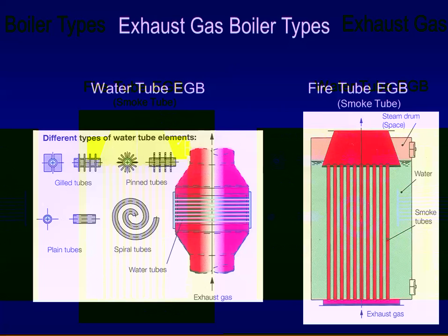Now, the next thing is keep an eye on the casing, and if it starts getting really hot, you have to cool it. What you're worried about is that the fire could cause an opening in the casing, allowing air in. Keep your circ pump on if you're a water tube type. If you are on a fire tube type, you make sure that they maintain the water in the drum.